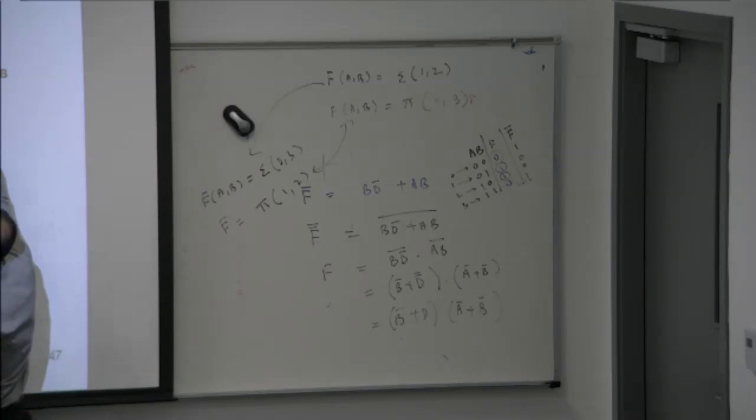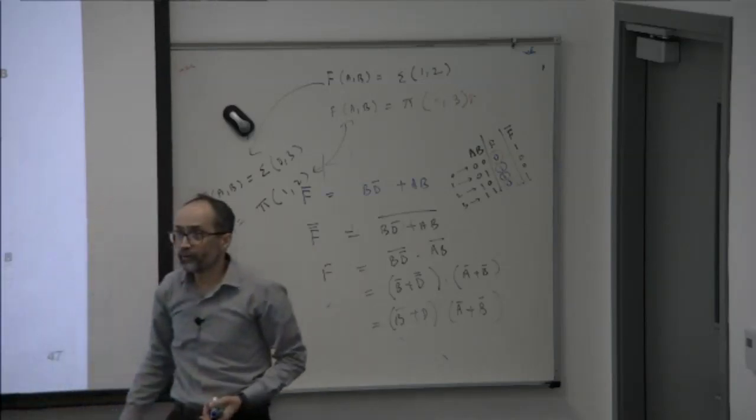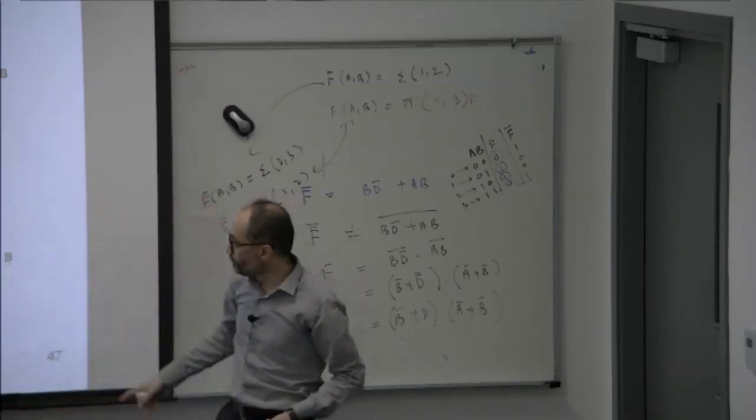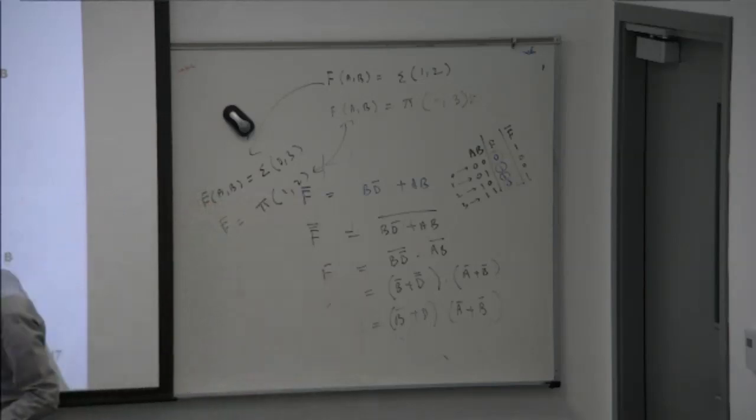These are all ones: 1, 1, 1, 1, 1. How many ones are there? 5. And then we put 6 don't care conditions. Why do we put 6 don't care conditions here? Because these are invalid BCD. Assume that we want to solve some expression for BCD, so we also include these don't cares.